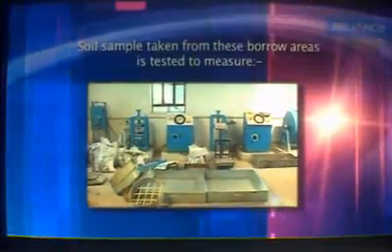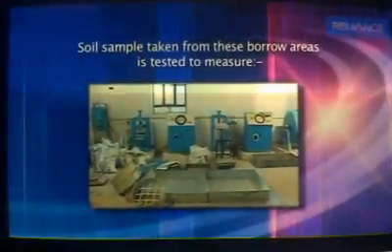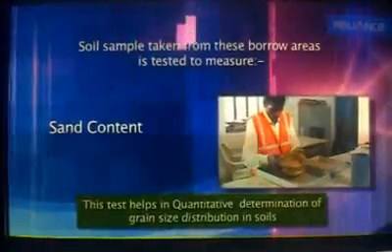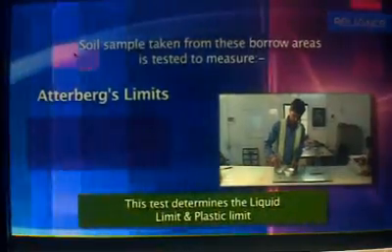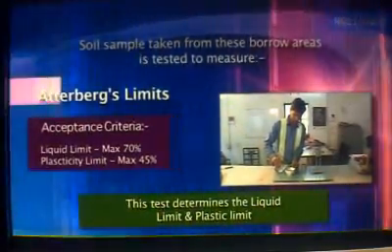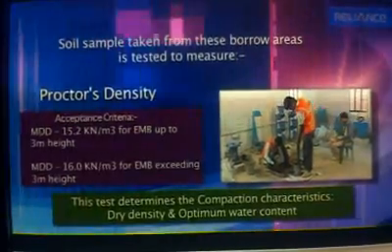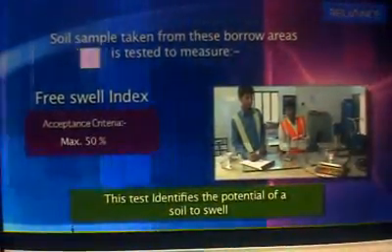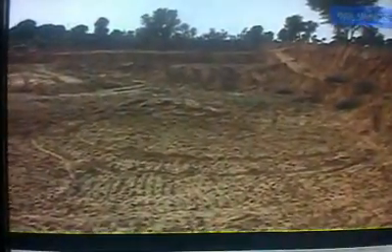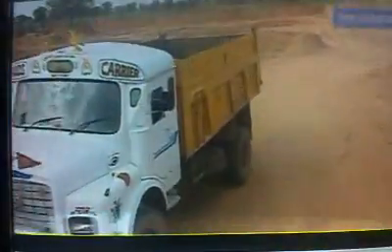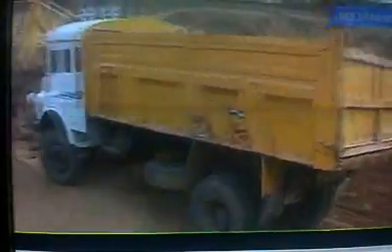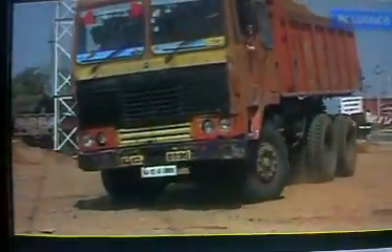Soil sample taken from these borrow areas is tested to measure sand content, Atterberg's limits, Proctor's density and free swell index. After the laboratory tests, the borrow areas are finalized for embankment. The soil for embankment is loaded in tippers and brought to site location.